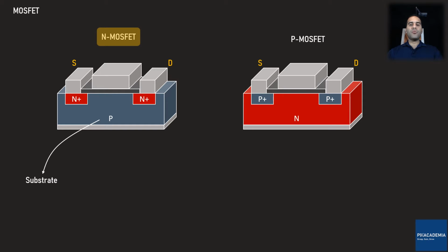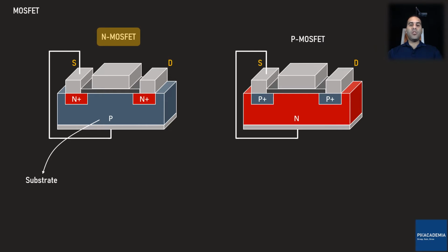The MOSFET structure is symmetrical, and you may think that there is no difference between the drain and source. In one sense, it is true, but the subtle difference is that to not allow the substrate to become floating, it is normally connected internally to the source. Later, you'll see why the source is called source and the drain is called the drain.